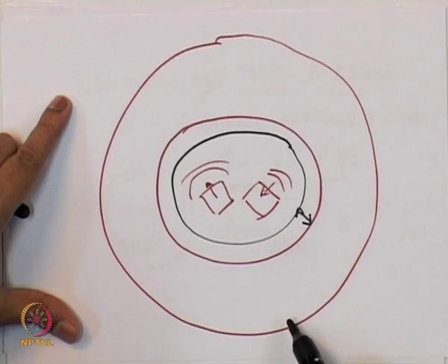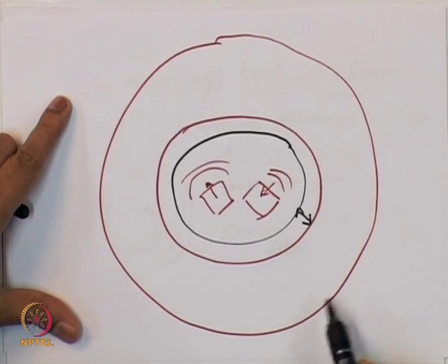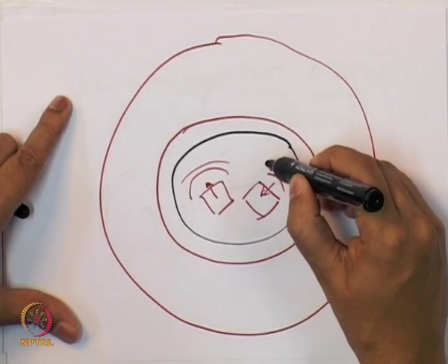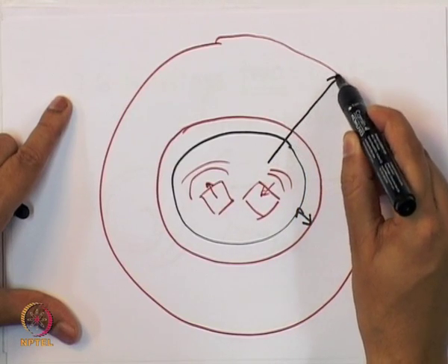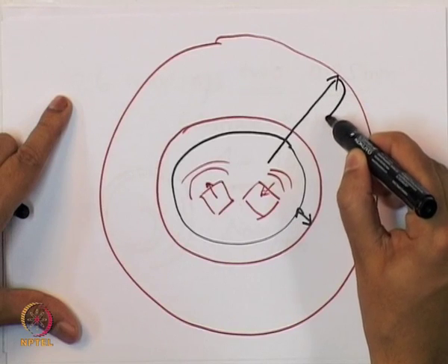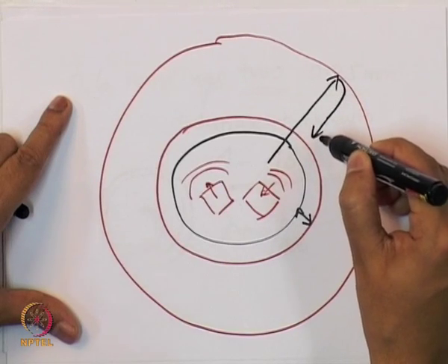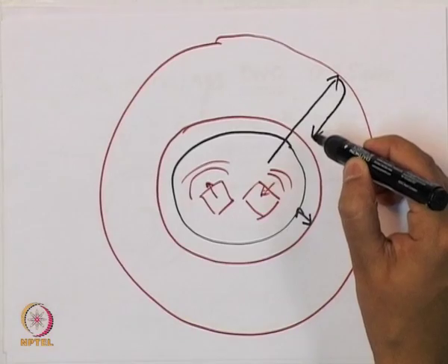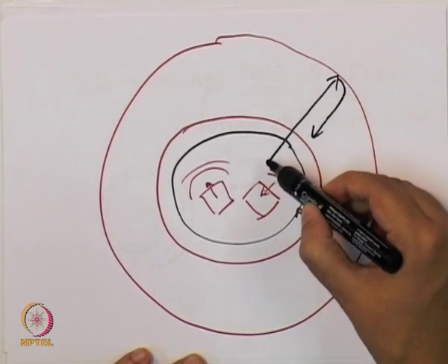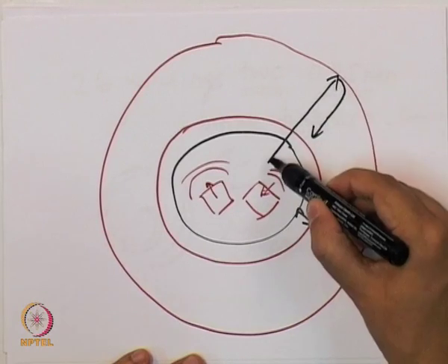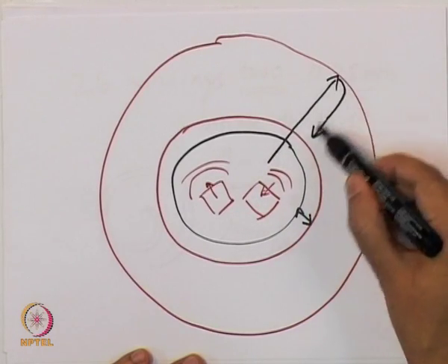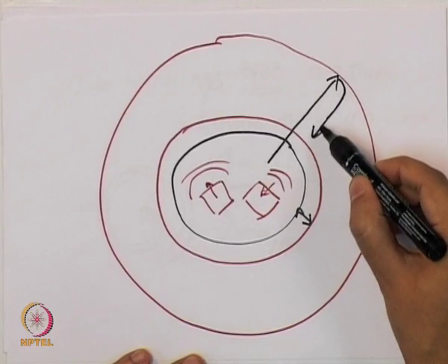So I use this one as a reference solution such that I make sure that the wave is going from here and then there is some reflection that is coming back. I stop the simulation before the reflection comes back. In other words, I make sure that I am only seeing the propagating wave, and the reflection is practically 0.